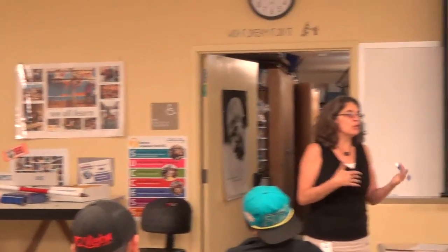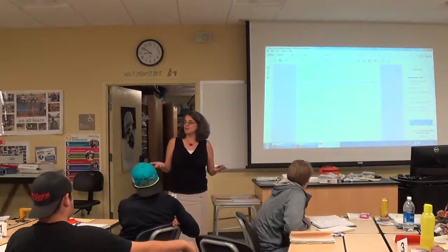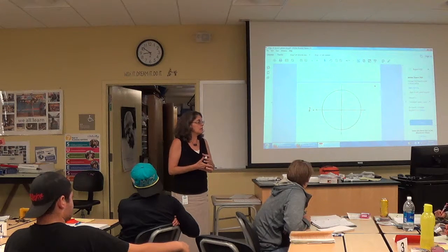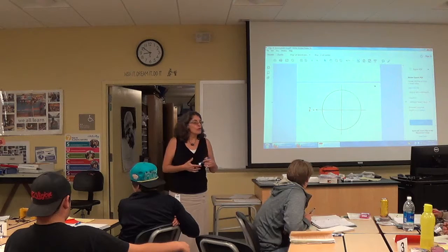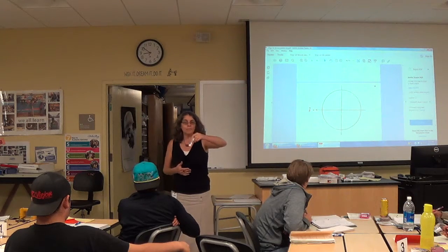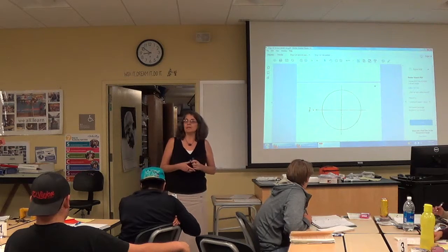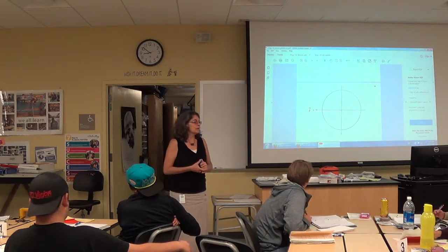And if yours was too small or bigger or smaller than 180, you had to do an adjustment, right? So you took the error. How did you calculate the error? You added up all the angles, and they came out to be 181 degrees. What's your error? 1 degree, right?